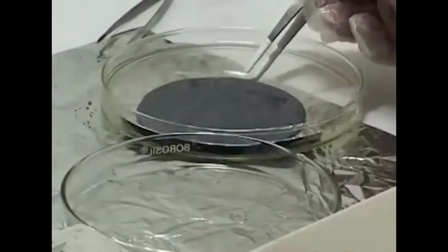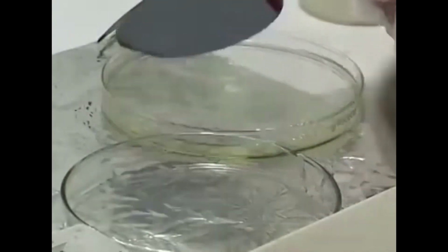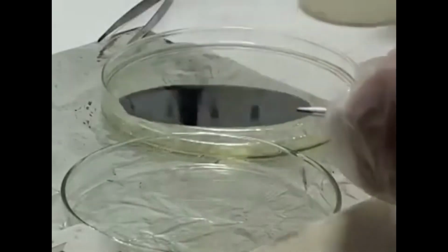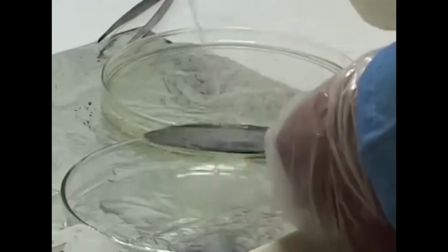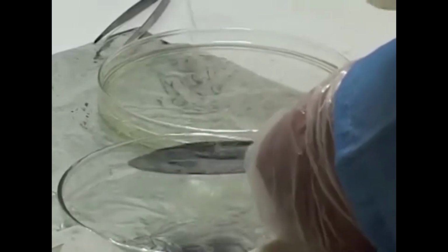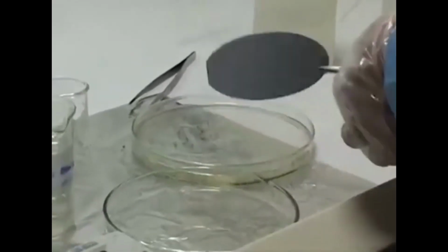Okay, so I am going to put this in for the first time and see. This is another beaker that we have put here for spraying isopropanol, and this bottle right here is the isopropanol. So I'm going to check this. I see that there is some clouding which has happened, which means that undeveloped resist is still present.